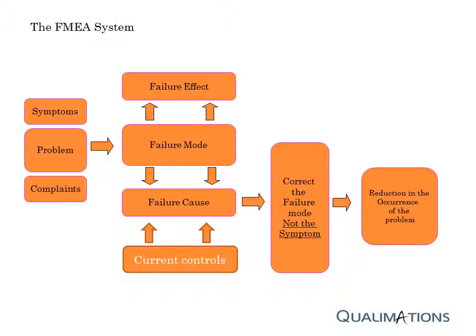A large number of failure modes identified for a single requirement usually indicates that the requirement is not well defined. The assumption is made that the failure could occur but may not necessarily occur. Consequently, the use of the word potential. Verification of completeness of the potential failure modes can be made through a review of past things gone wrong, concerns, reject or scrap reports, and group brainstorming.